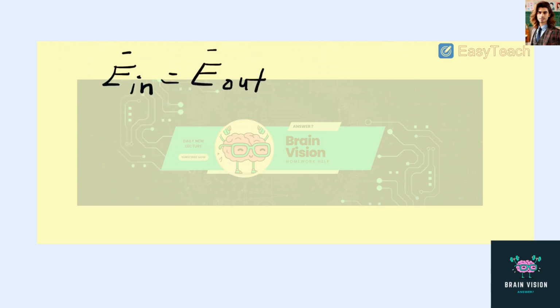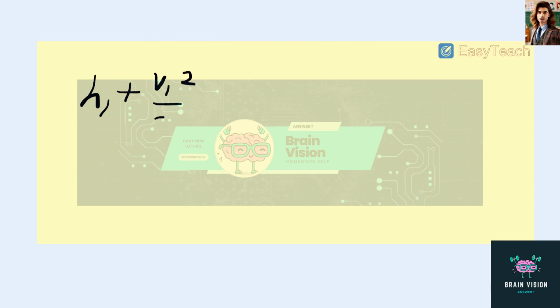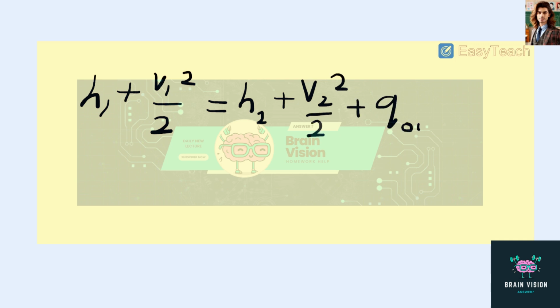We can break this up into its constituents: E dot in is equal to H1 plus V1 squared over 2, so this is energy due to enthalpy and velocity that is coming in. And then we have that set equal to the energy leaving due to enthalpy, energy due to kinetic energy, but also the heat that is lost. So that's going to be Q out.